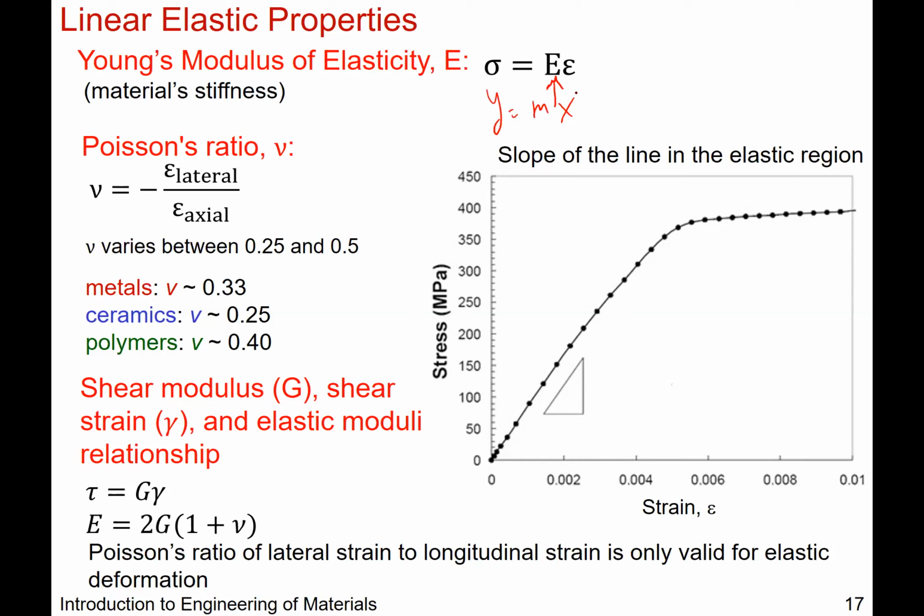It's a slope. Knowing the relationship between stress and strain, given that it's related by the modulus of elasticity, or Young's modulus E, we know that looking at a stress-strain curve like this, we're really talking about this region, where we can sort of eyeball a linear line of some sort.